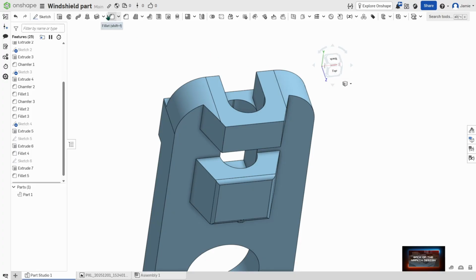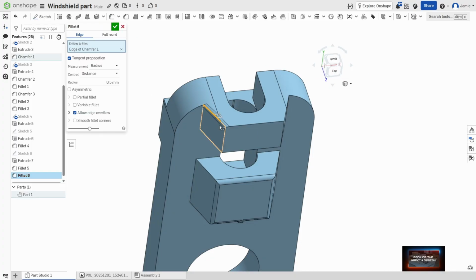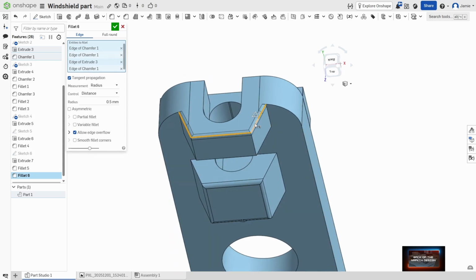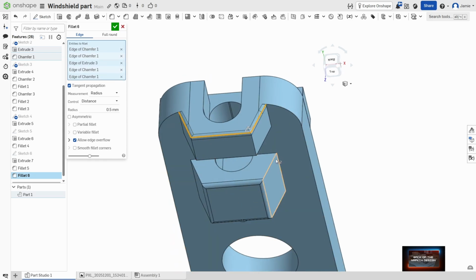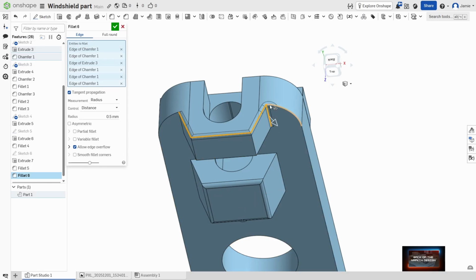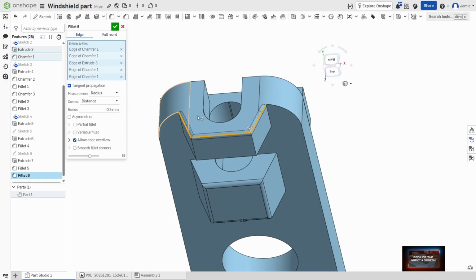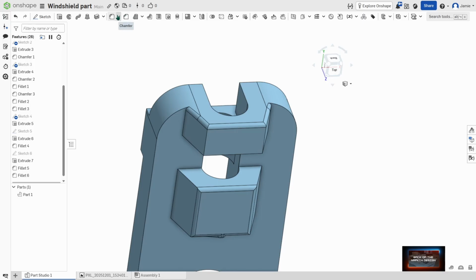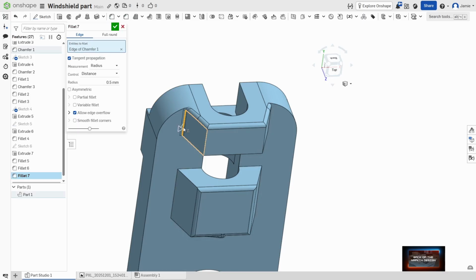So let's create a fillet. Click there and there. We can actually continue that fillet and then do this side. Looks great. It looks like they got a fillet on the bottom here too. I don't want a fillet on that edge right there. That looks goofy. So let's hold down shift and unselect that guy. First, I'll just do this one fillet, and then I'll put in another fillet, and then hopefully finish that guy right there. Yep, perfect.